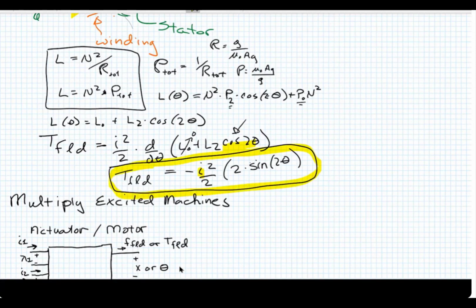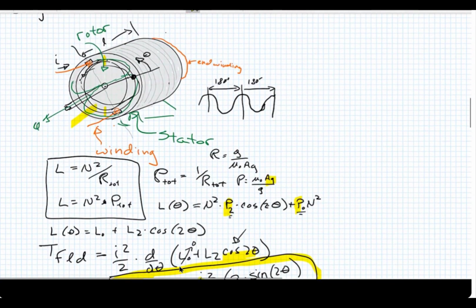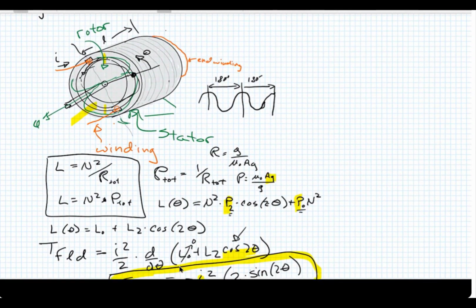So it's quite simple, right? And I gave you a couple of examples. So how come the torque is not dependent on the radius? Because we built it into the permeance variables. We could have gone in and done some geometrical stuff, and we would have come up with it, we could pull that out. It's buried in here. It's inside here, because the area of the gap is this. Here's the gap that you're talking about.